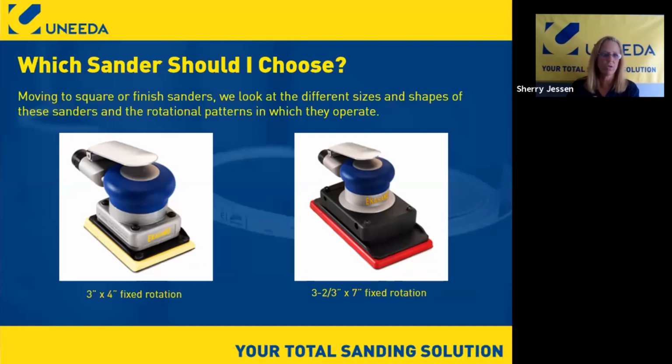Drawer boxes. You can drop in and go corner to corner on a drawer box, where before we were having to sand with a 5-inch and then come back with a block, or go straight to a block and do all of our finish sanding in between coats. The sander on the side is a 3 2/3 by 7, which is a larger footprint.